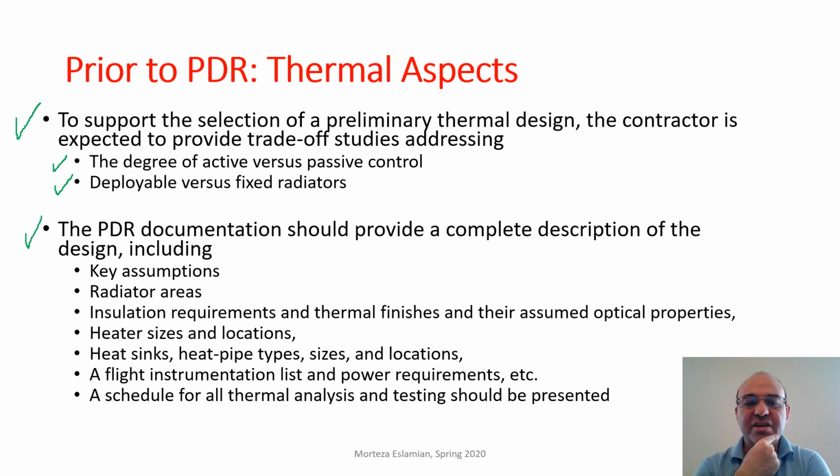Key assumptions, radiator areas, insulation requirements, thermal finishes, coatings, their assumed optical properties, heater size and locations, heat sinks, and heat pipes, if heat pipes are used, sizes and locations. So this is like a real design, but it can be further improved in the next step, and it can be further verified in the next step.